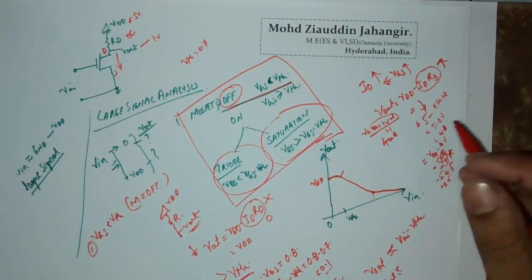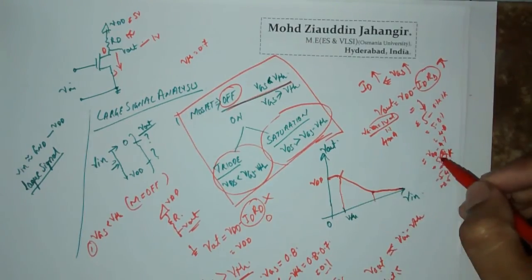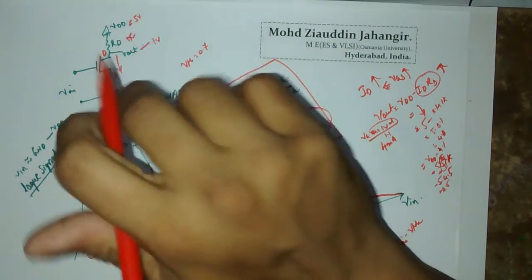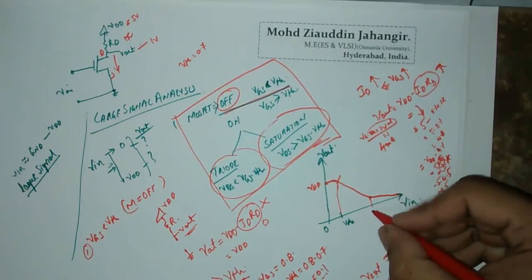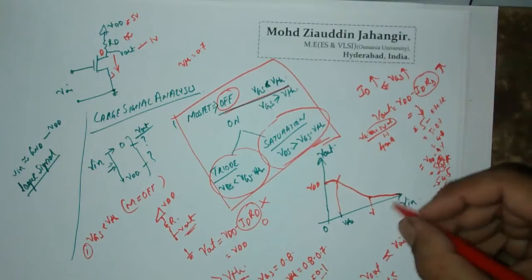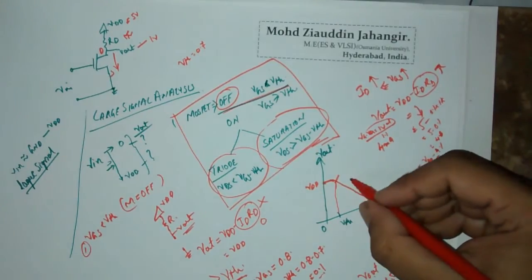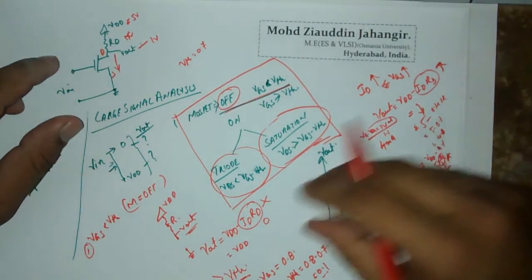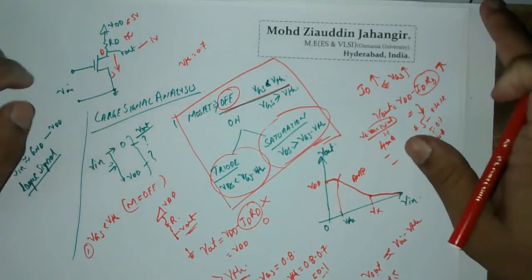Therefore for a large signal, there are two limits to be considered. First is this limit, and other is this limit. If you use this circuit for amplification of voltage between these two ranges, let us call this Vx. So between VTH and Vx, your circuit is going to behave like an amplifier, and if you go out of this range, then you are going to get a clipping action, or you are not going to get an amplification. That is what happens.